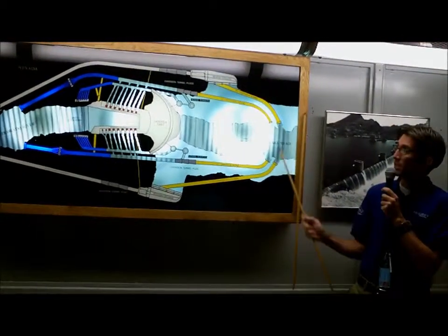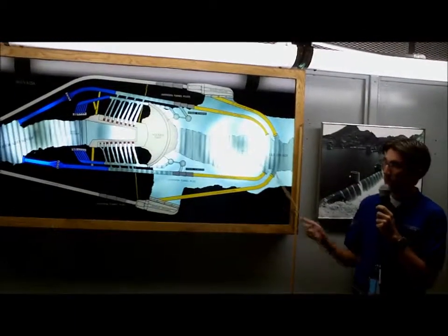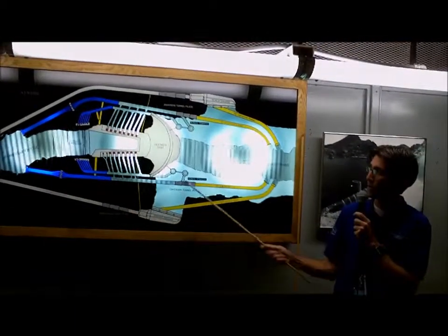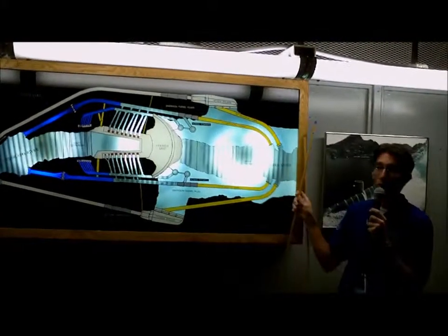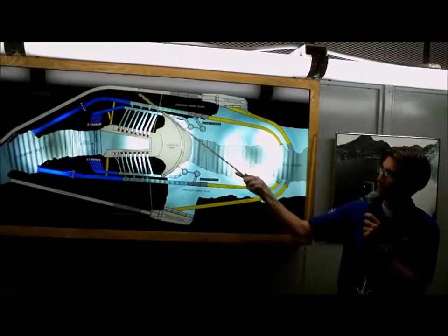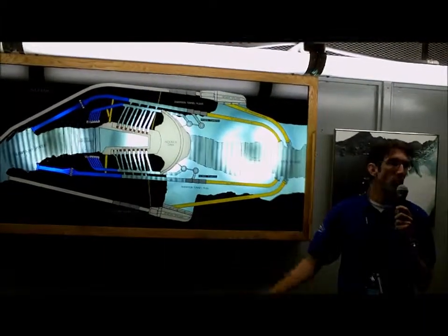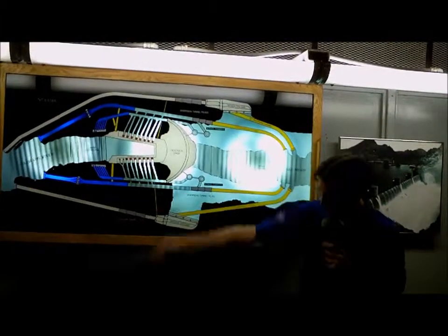So now each of these is sealed at its entrance with a 50 by 50 foot steel bulkhead gate, and each tunnel has a 400-foot concrete plug within it. So now these yellow stretches are no longer in use. However, the remaining outer stretches of these diversion tunnels, this is where they connected the new spillways to. And you can see that better on the diagram to my far right on the wall.